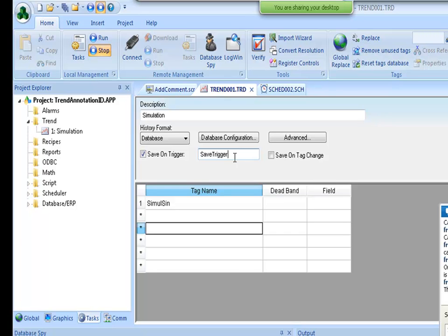And obviously, it also depends on the computing power and everything else to make sure that this time period will be respected. Since it's not a real-time software like a PLC, most likely the difference between the samples will be 100 milliseconds or 105 milliseconds, 100 milliseconds again, 120 milliseconds. So you can experience some variance between the samples there when you go to anything below 1 second.